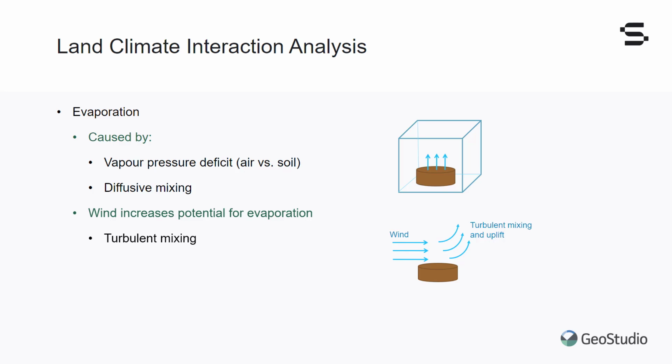Wind generally increases evaporation potential, as wind blowing across a surface creates turbulence and enhances vertical mixing of air that carries latent heat, or water vapor, and sensible heat upwards. Vegetation may decrease evaporation by increasing surface friction, which limits wind effects, and by providing shade, which decreases the energy inputted from the sun that contributes to evaporation. Thus, potential evaporation may be dependent on the moisture content and diffusive mixing in the soil, incoming energy, wind speed, and the vegetation soil cover fraction.